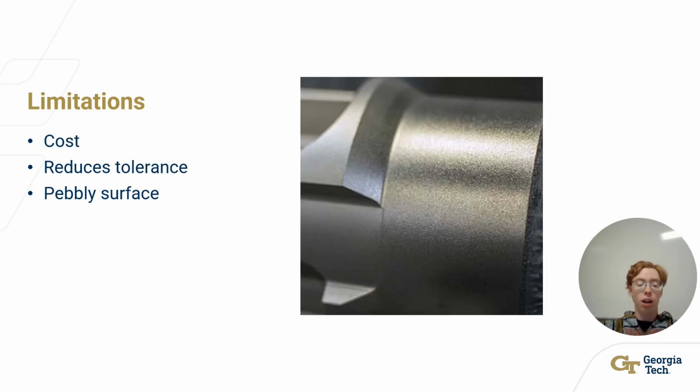The main limitation of shot peening is the cost. Shot peening is a surface treatment and is usually conducted after all machining is complete. This means that it is an additional cost due to an additional process.